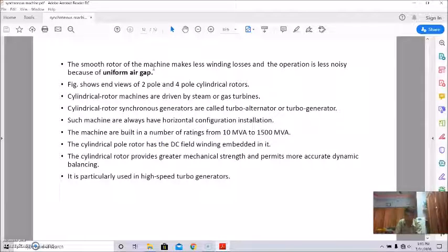The armature winding can also be braced better mechanically against high electromagnetic forces due to large short circuit currents when the armature windings are in the stator. This is one way to get better mechanical strength to brace the armature winding.